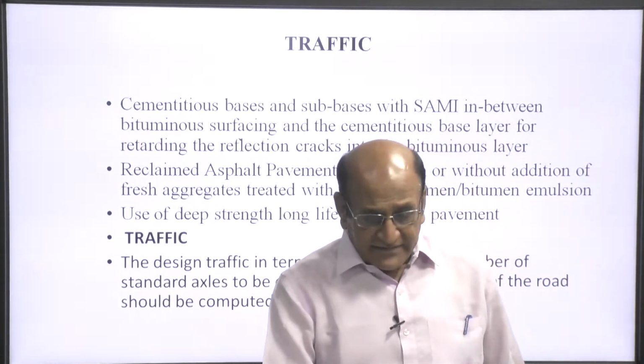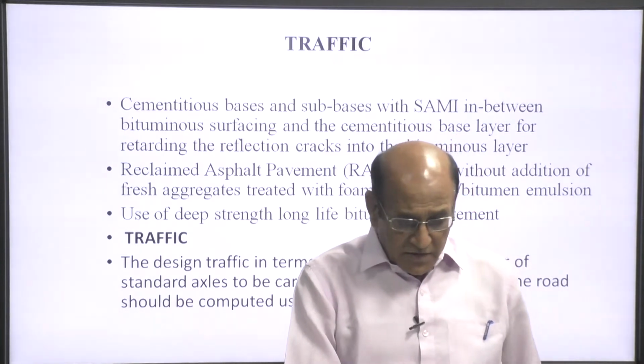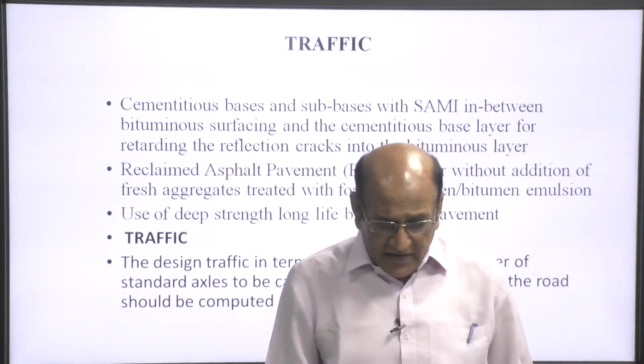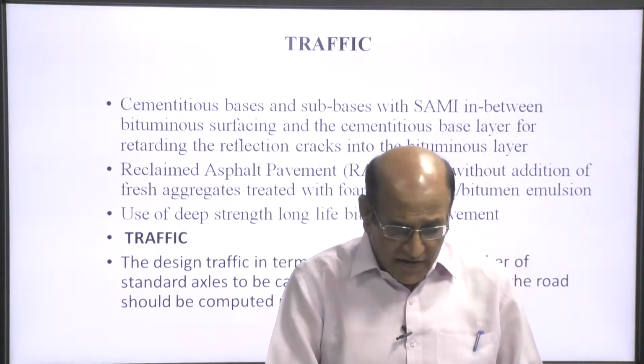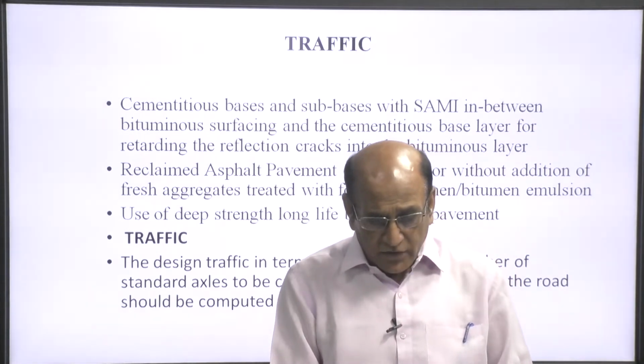Cementitious base and sub base with SAMI in between bituminous surfacing and cementitious base layer for retarding the reflection cracks